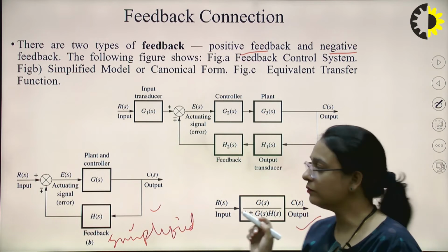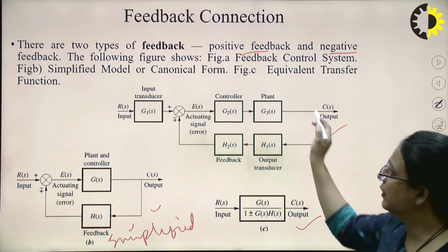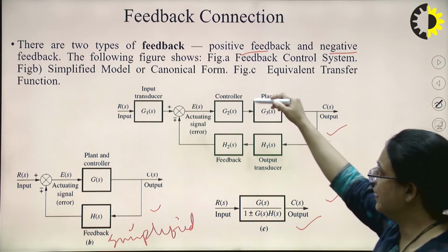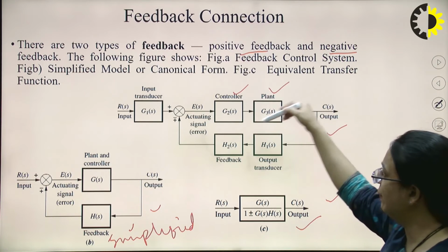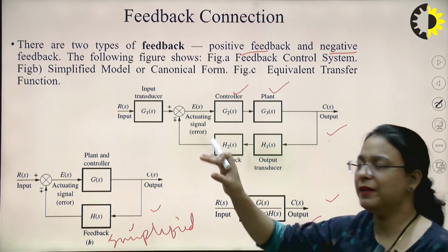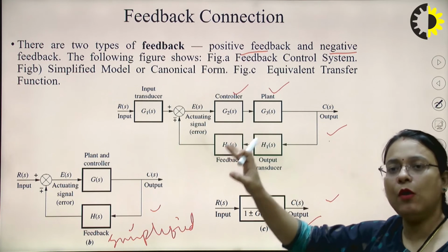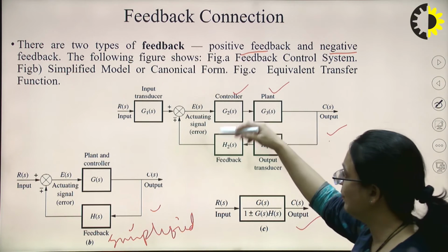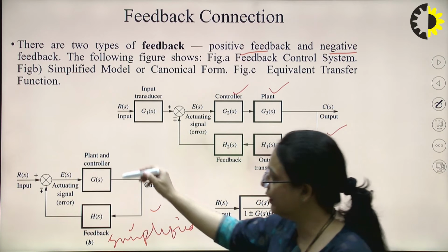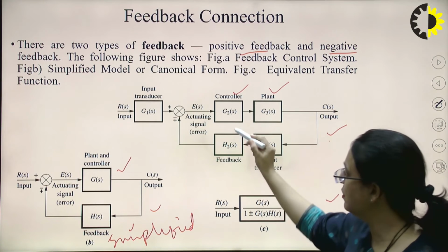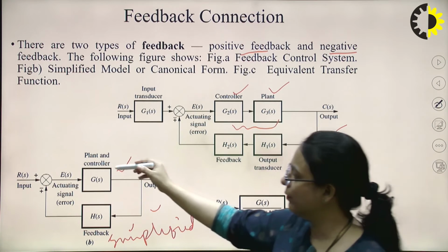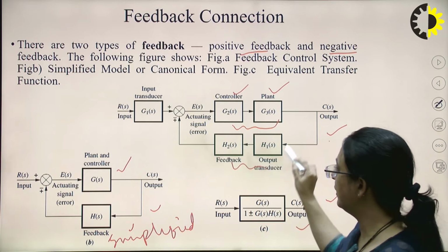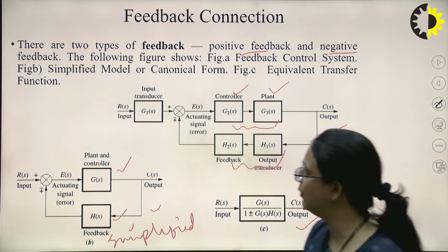So this particular control system is having a controller, it is having a plant. Every element is being represented by a block which is containing the transfer function, right? And now, after simplifying, we are representing it with a single block. Since these are connected in series, we represent them with a single block. Similarly, these are connected in series, we can represent them with a single block again.